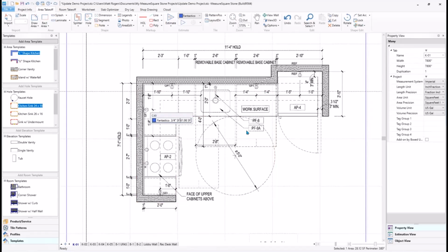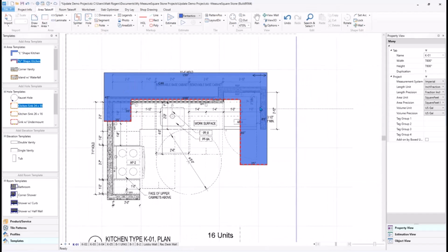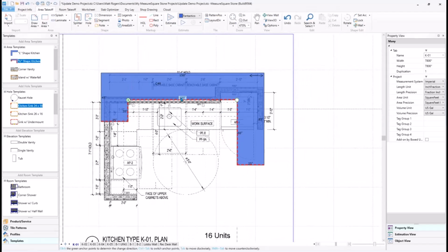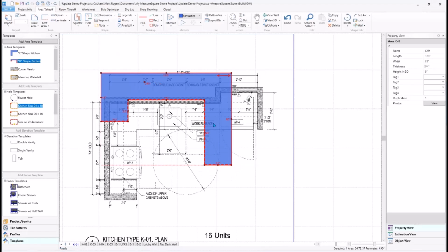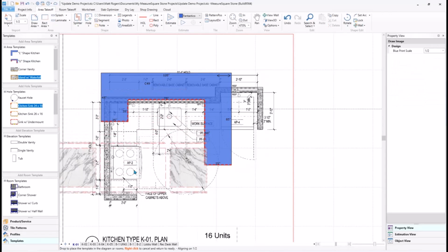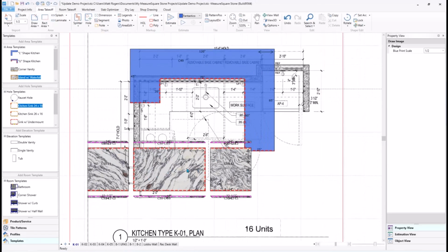So I'm going to delete this piece here and bring in this U-shaped piece here instead. Again, we can use this in a lot of different ways. We can pull in this edge here as well if we want to change this to 70 inches. Again, we'll just change this down here back to 25 to make that the same depth for our countertop here. And I can also bring in something like this island with this waterfall. When I bring in this island here, for example, you can actually see we have all the edge details going around our island and down the waterfall edges. And we also have a miter edge going around all of our laminate leg pieces here as well.